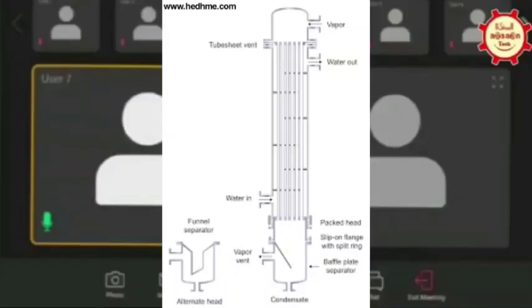Any open points? Today I was modeling a vertical heat exchanger, and when I mark up a nozzle in the top bottom channel, there is an error. A new error is coming in the output report that the nozzle location reinforcement area is incorrect. The location area is coming incorrect.